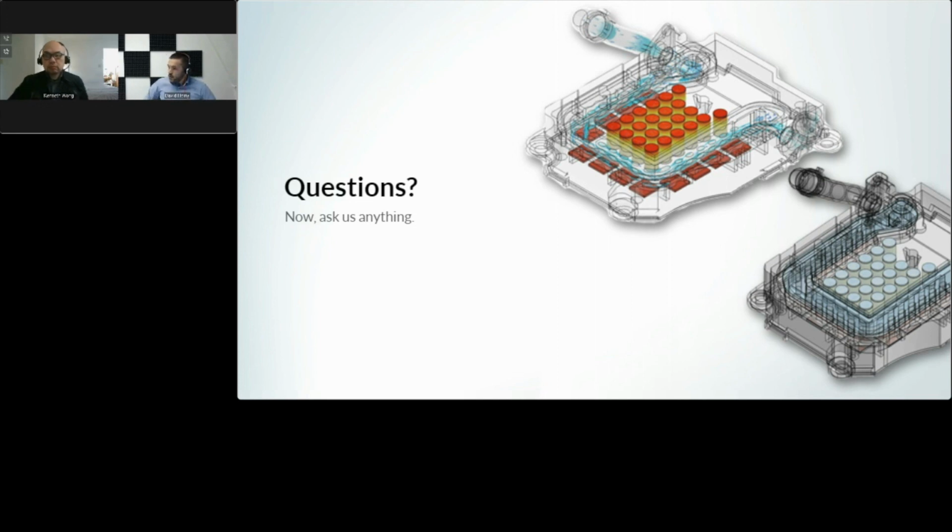So a strong local GPU helps, but is not required. The reason why I say it helps is that there are certain aspects in a simulation workflow, such as what we just saw, the assignment of boundary conditions and rotating a CAD model, where we do leverage the local GPU. In this case, it's not pixels that are being streamed, but triangles are being cached in the browser, and we can leverage the local GPU.